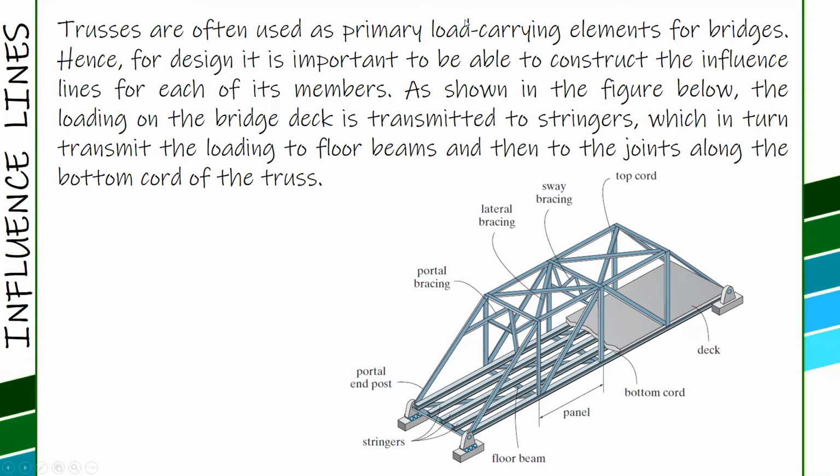As shown in the figure below, the loading on the bridge deck is transmitted to stringers, which in turn transmit the loading to floor beams, this one, and then to the joints along the bottom chord of the truss.